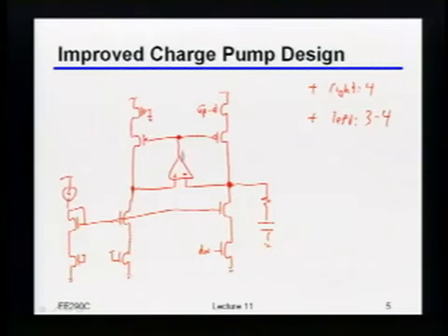So you just have to make sure that the op-amp has high enough gain bandwidth relative to the bandwidth of the loop itself. And the bandwidth of the loop is limited by your reference frequency, and compared to what you can do with the circuitry, that's not too hard to achieve. But you can't obviously ignore it. You have to make sure that the feedback loop really is stable. So it need not be very high bandwidth, it need not be up to the bandwidth of the loop.